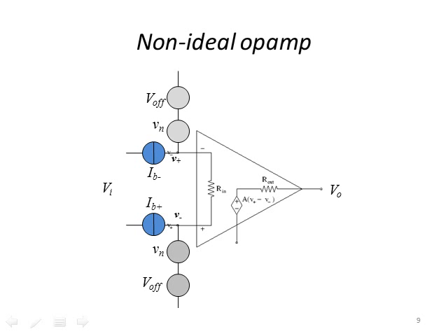We have voltage sources to represent the offset voltage, the input noise voltage, which is lowercase vn, the finite currents at the input terminals IB minus and IB plus, the finite input impedance Rin, the finite gain of the system, which is represented by a voltage source with a gain A, and then our output impedance, which is not 0 and is finite.